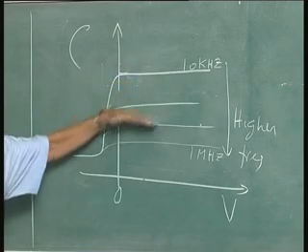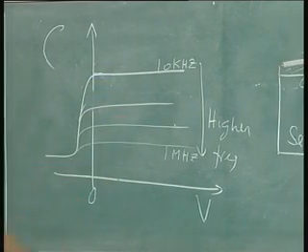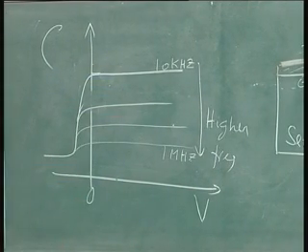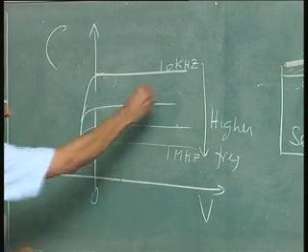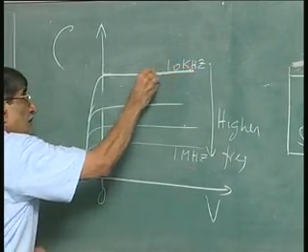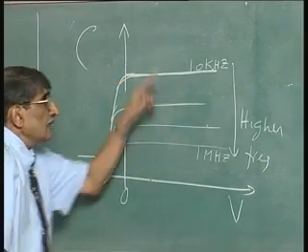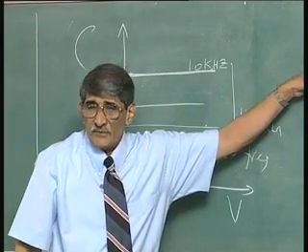There is frequency dispersion. Measure the CV at different frequencies, and the capacitance is different, which is not supposed to be the case ideally. Ideally, the capacitance should only be one value. The high frequency itself should show this. That should be the capacitance of the oxide.